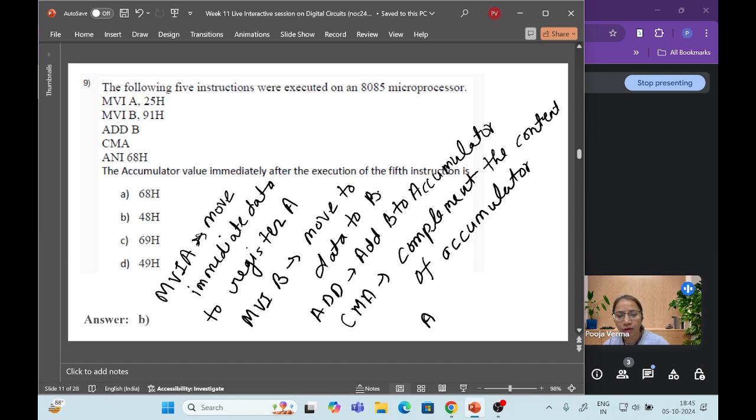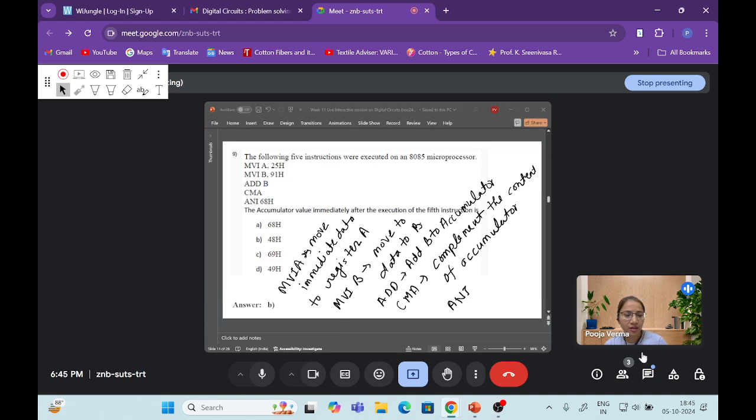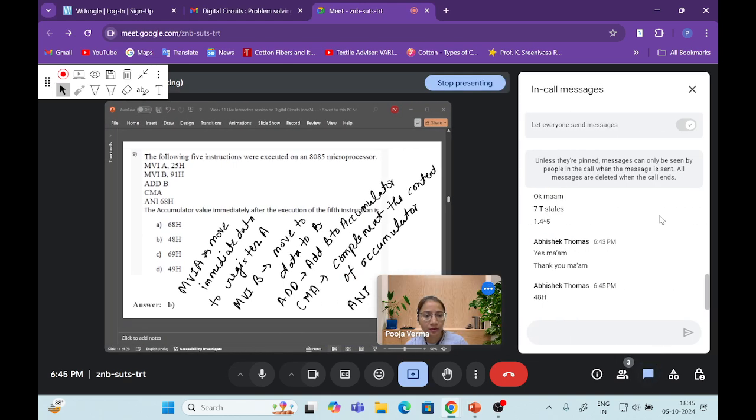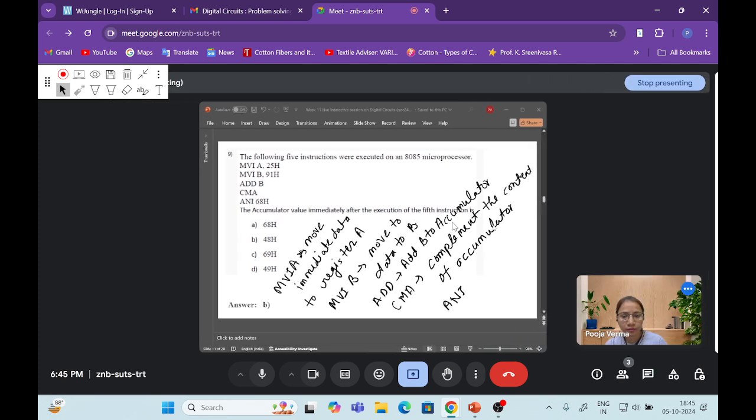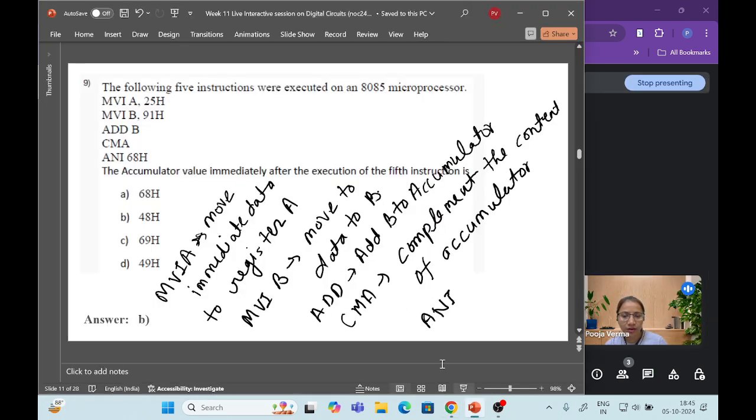Now, what does ANI do? ANI 68. The answer is 48 H, but how does ANI work? What operation do we perform? Logically AND the content with the accumulator.